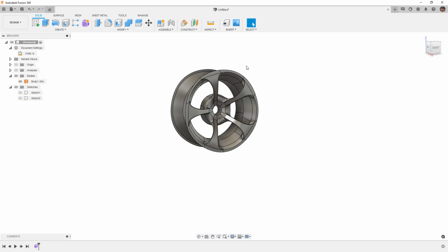Again, it's not a perfect workflow. It does take a lot of time. And my suggestion would be to use some of the techniques that we've learned with things like creating a surface extrude and then attaching your form body to it, because that would allow us to create a perfectly revolved cylinder or barrel for a rim.